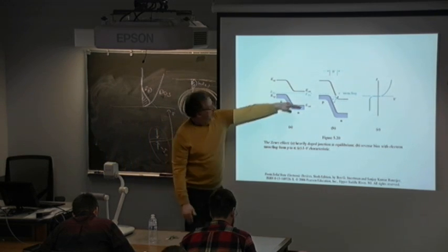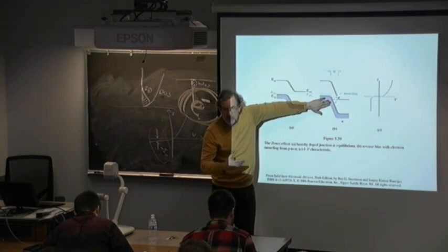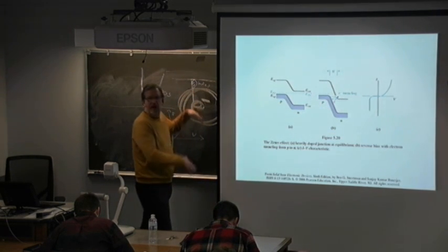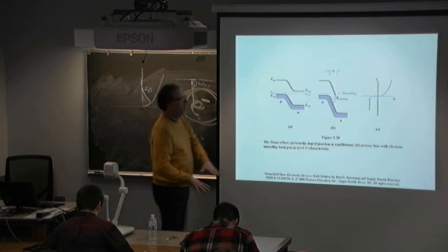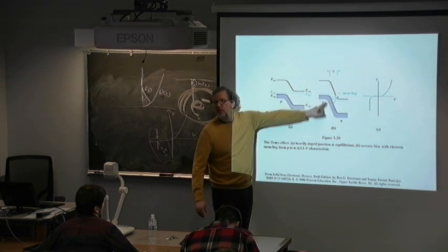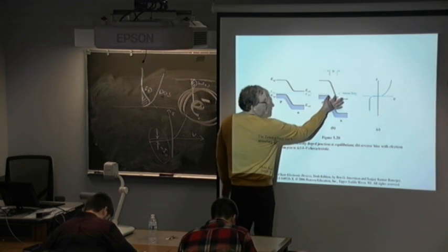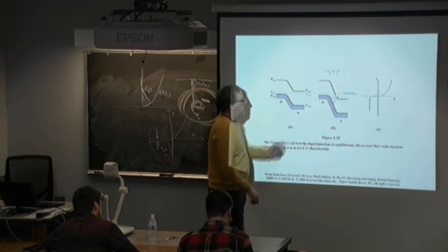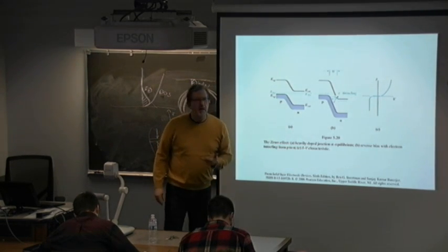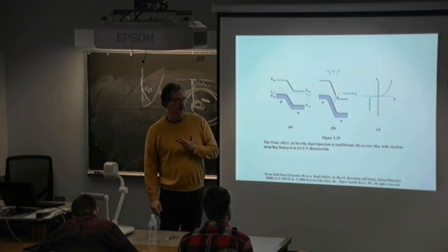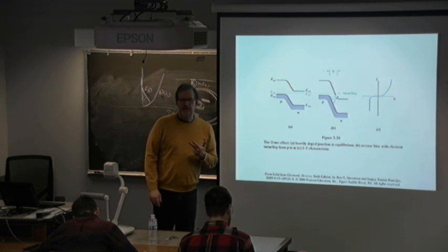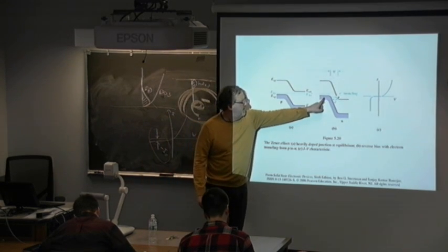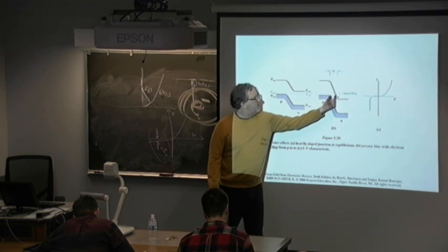So there are all these electrons even though it's the P side. It may sound a little strange, but normally these guys are not in play. They're usually buried so far below that they're not in play. But in this particular unusual circumstance, this is very narrow, and they can quantum mechanically tunnel across. So what are the conditions for tunneling? Stefan? Availability of carriers, empty space adjacent, and a small distance in between, yes.